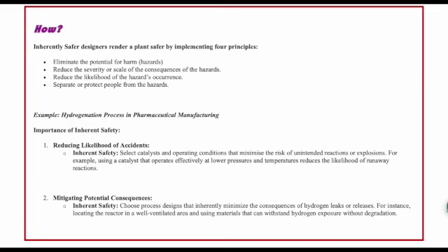What is actually done is that the oil is mixed with the catalyst, usually nickel, and then heated to a temperature between 140 to 225 degrees centigrade and exposed to hydrogen while being continuously stirred. The mixture is then mechanically agitated at the desired pressure, which is usually 60 psi, as mentioned. Now, this is the process that your company will be taking care of, and it will be happening in big containers, not small ones.